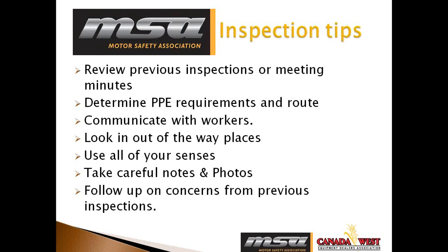it can be corrected. When it comes to photos, if you're on site at someone else's facility that you may have been invited to, get permission first before you take photos, as opposed to just taking the photos. Photos are an excellent item that you can have on your inspection because it really adds to your inspection report. And you want to follow up concerns from previous inspections. If the area was inspected before and some areas may have been documented and the items have not been addressed, you want to take some time and ensure that they are followed up or at least in progress.